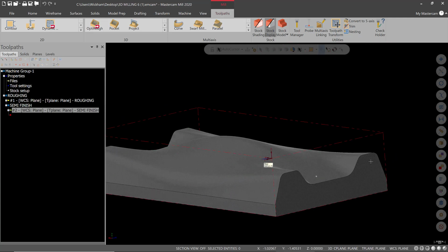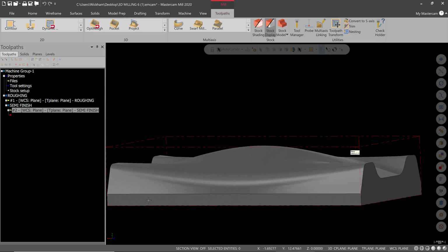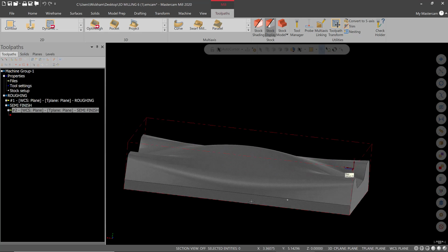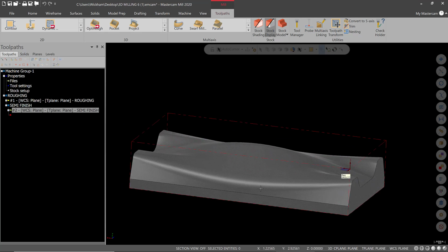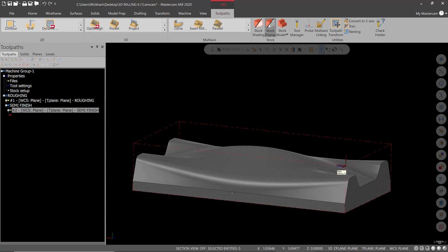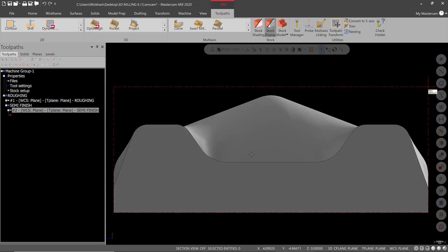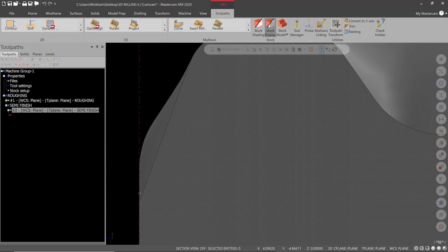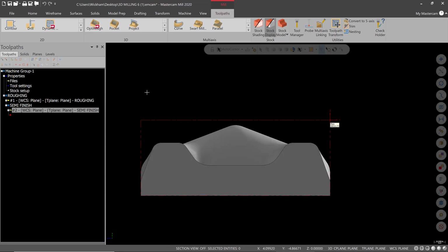Now, obviously, the 3D toolpath is not going to do much there. It's not really 3D. But what happens is it machines it all at the same time, and you have better luck. Now, is that realistic? Do you need to do that? It all depends. Since this wall is vertical and this wall is vertical, that little red line is just saying that there's no material there to 3D machine because it's already gone. If you look at this in the right view, again, you can see how high that wall comes. That material is already not even there. That's why it's not writing code there.